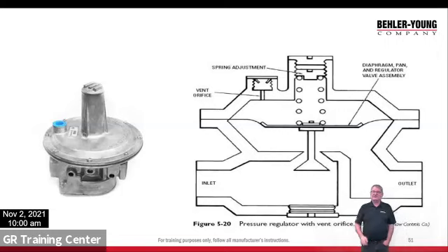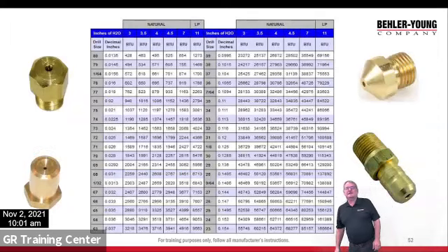Okay, but again, that little vent there, in some cases, it will be going outside, all right, on bigger stuff. That can be a problem too, because if that vent gets plugged, that little diaphragm can't move anymore, right? So we may have a problem. On propane, you might get a little bit of ice buildup in that vent. Okay, that would stop this from working.